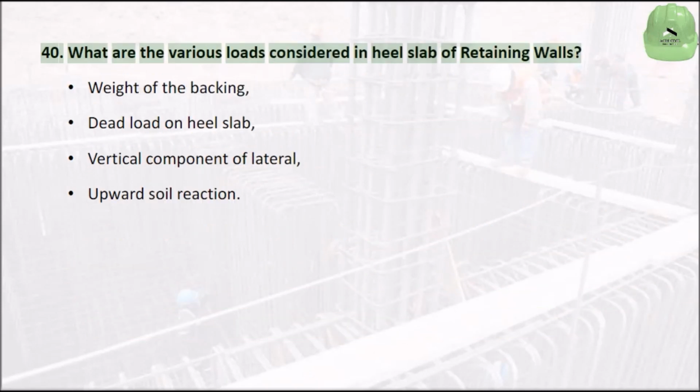What are the various loads considered in the heel slab of retaining walls? Weight of the backfill. Dead load on the heel slab. Vertical component of lateral pressure. Upward soil reaction.